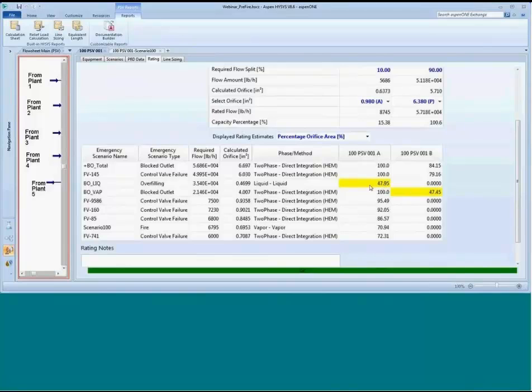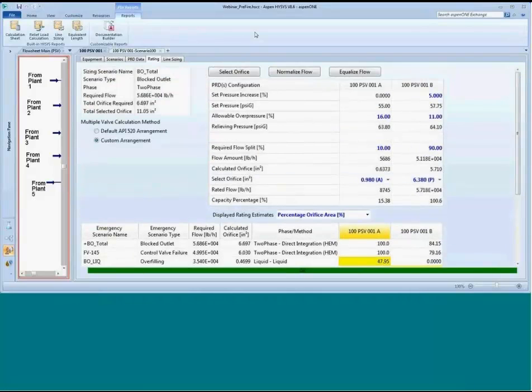So this is sort of an engineering judgment, whether you're okay with using 50%. I am, so I'm going to stop here and say using 50% of the PSV capacity is pretty good. You really get worried when it gets down into 30, 20, 10%. That's when chattering can really become a real concern. So that's how you set up different valves.